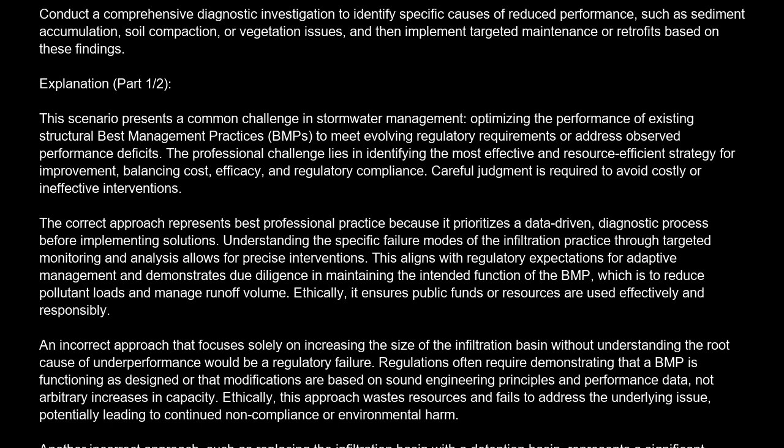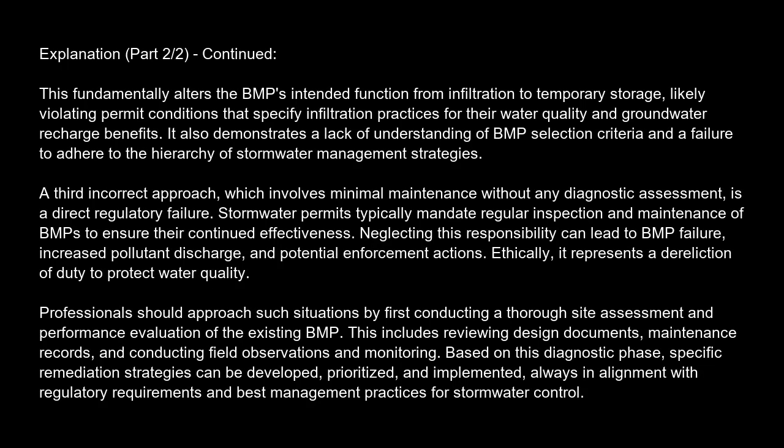Another incorrect approach, such as replacing the infiltration basin with a detention basin, represents a significant regulatory and ethical failure. This fundamentally alters the BMP's intended function from infiltration to temporary storage, likely violating permit conditions that specify infiltration practices for their water quality and groundwater recharge benefits. It also demonstrates a lack of understanding of BMP selection criteria and a failure to adhere to the hierarchy of